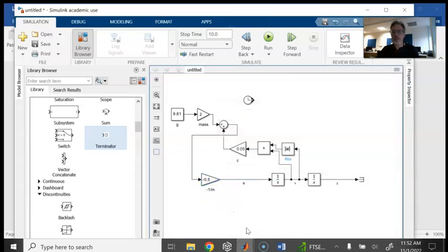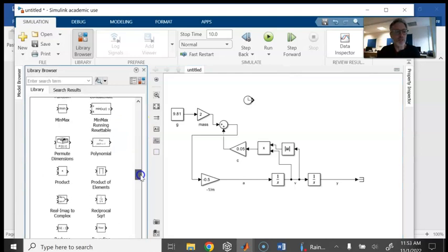Okay, and now I've got a complete system. So at this point I can stop and say, hey, whatever v is at the current time, I can use that along with mg and these other gains to make an acceleration signal, which I can integrate twice and get the velocity y, sorry, get the position y. If I want to look at this, plot a graph of it, there's two things I can do.